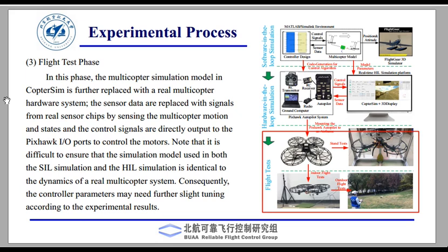Flight test phase. In this phase, the multi-copter simulation model in CopterSim is further replaced with a real multi-copter hardware system. The sensor data are replaced with signals from real sensor chips by sensing the multi-copter motion and states, and the control signals are directly output to the Pixhawk input-output ports to control the motors.